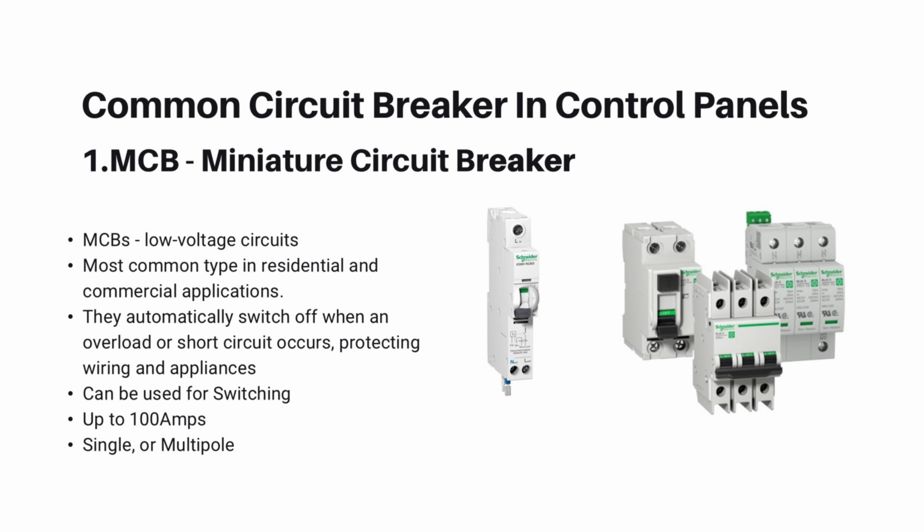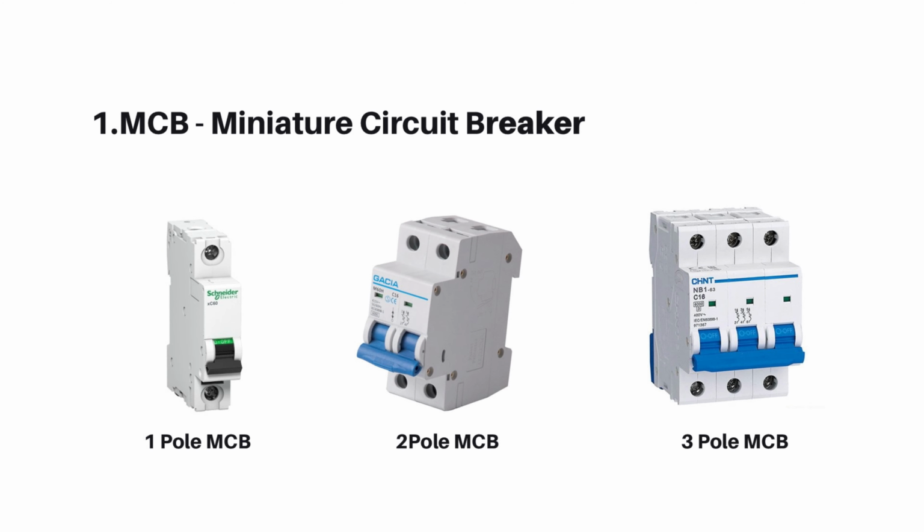They are used for switching on or off as well. Their rated current is up to 100 amps maximum. MCBs come in single pole, double pole, or triple pole. For double and triple, each phase line is connected to its own pole.